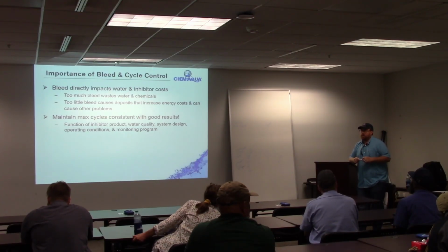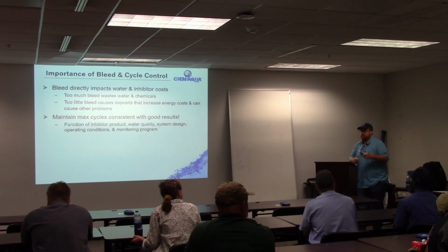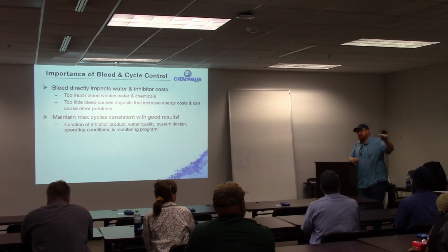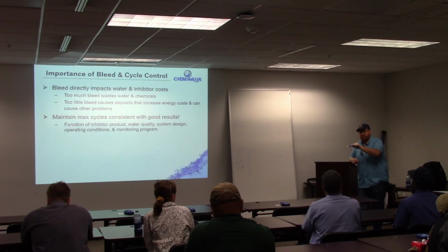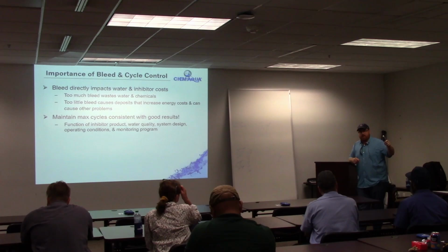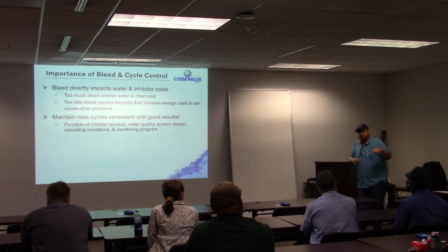One thing that is impacted by your location in the city is the city water chlorine levels. So the city has different injection points in different areas. You have some areas that have very little total chlorine in the city water. You have other areas that have really high levels because they happen to be really close to an injection point. So we've had customers who have had issues with some of their domestic water lines with corrosion because of the city water chlorine levels. They've had to put in activated carbon filters to remove the chlorine.